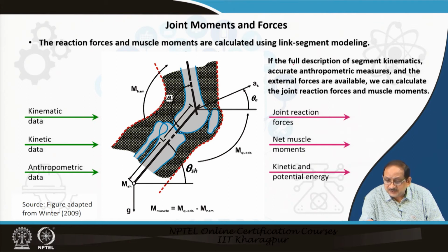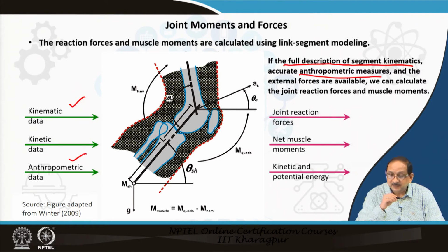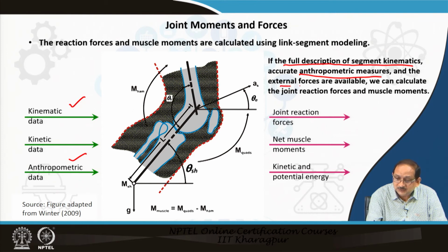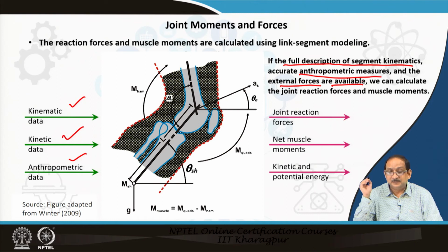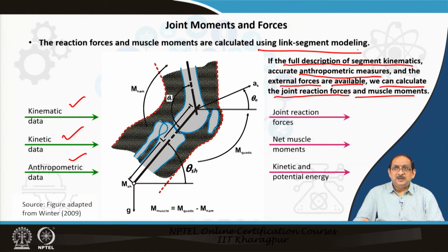If a full description of the segment kinematics, accurate anthropometric measurement or data and external forces are available, we can calculate the joint reaction forces and moments using the link segment modeling approach.